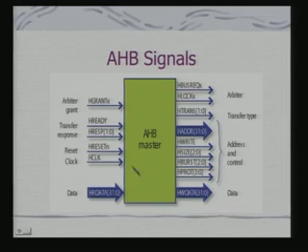So, what are the AHB signals? If I look at these as an AHB master, this is a kind of conceptual model. Any CPU or a DSP can be an AHB master. The whole issue is that the bus interface unit of the AHB master should be compatible with these kinds of signals. Already we have seen that it will generate the request. This is a request to the arbiter. It will get the grant from the arbiter. If the slave wants to introduce a wait state, this is the input which will come through the wait state. The response gives the status, okay, the response from the slave,